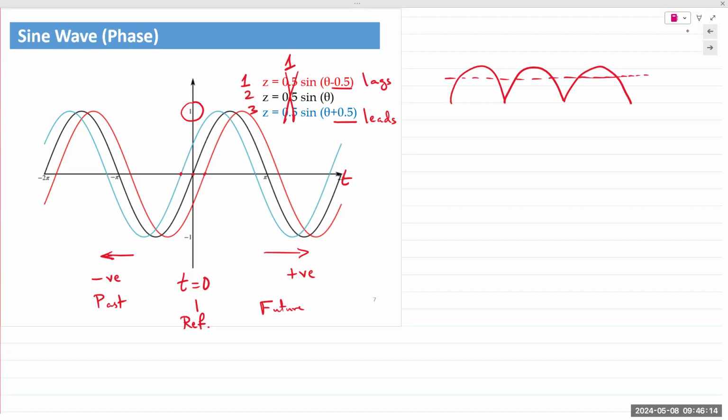So what they did was, they said we can't take the average of the waveform. So what we will do is first square the waveform. We'll take the square of the waveform, then we will take the average. And because we took the square and then took the average, at the end of our result we will take the square root. Okay?